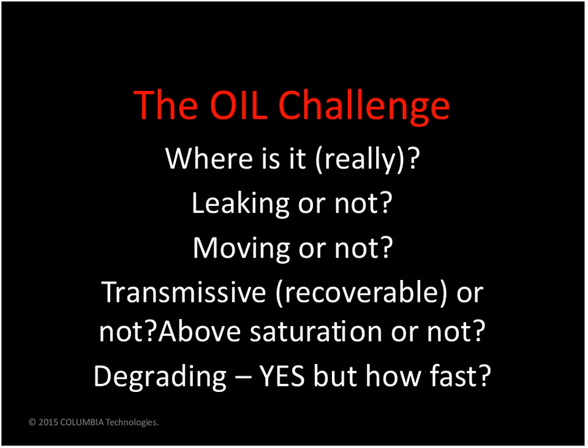So then the question is, is it mobile? Within the footprint of the remaining oil, is it mobile? Can we recover it? Is it transmissive? Can we suck on it and actually recover it? And therefore, we ought to have skimmer systems out there or other types of recovery systems. And then you kind of walk back up that continuum. Then you get to the point, do we really have LNAPL, or do we have dissolved phase, or do we just have residual phase material that's not above saturation?